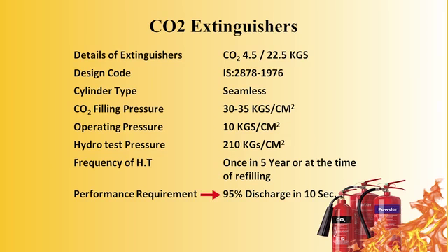And performance requirement: 95% discharge in 10 seconds. How could you know the performance of the CO2 extinguisher which you are using? Performance required is 10 seconds. In 10 seconds, 95% of CO2 gas is to be discharged to extinguish the fire.